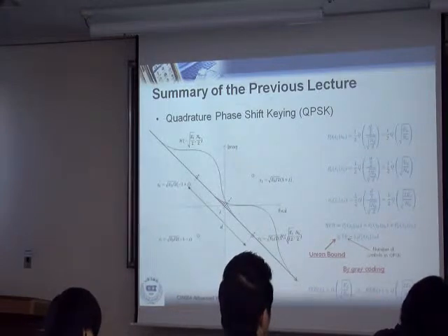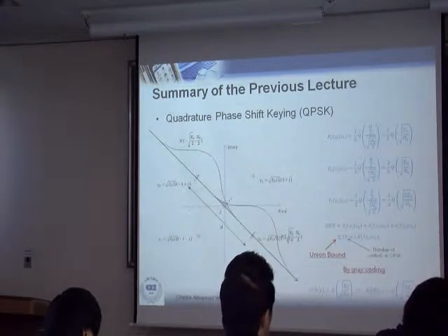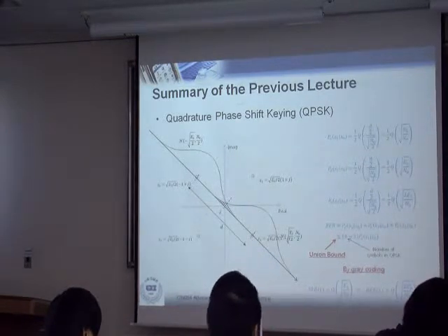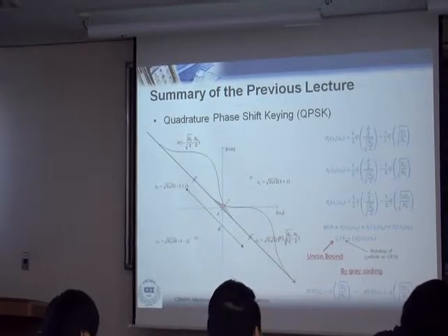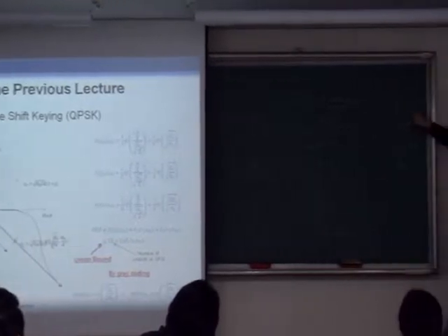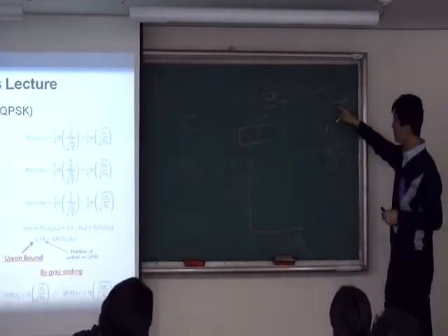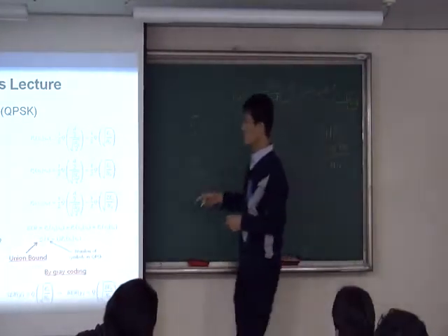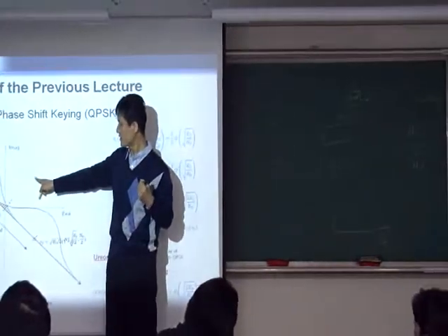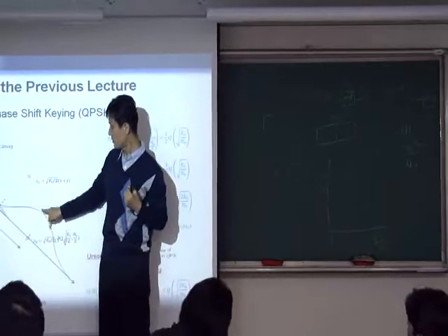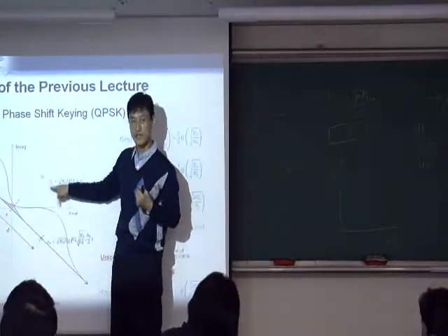That's what you transmitted over there. And after you add some noise and also the fading channel, you receive another complex value. Let's suppose that we only have noise. In this case, let's say in the transmitter, you transmit this one. In the receive antenna, let's say you received some other point, maybe here, because of this noise, right?